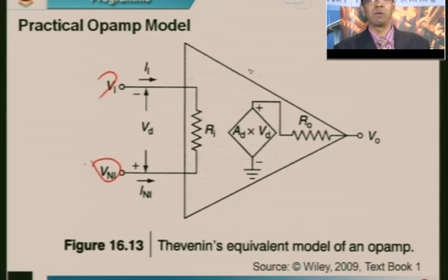Signal conditioning is the one which comes to mind straight away, meaning amplifying a weak signal, or a low noise amplifier. We use them in signal conditioning. We use them for integration and differentiation. Plus, we can also use these op amps for operations like summing, which is adding, subtracting, doing a comparison, and it can also do filtering, which is basically a low pass filter or high pass filter. Because of all these operations that this op amp can do, we call it an operational amplifier. Now, coming back to the actual model of this op amp.